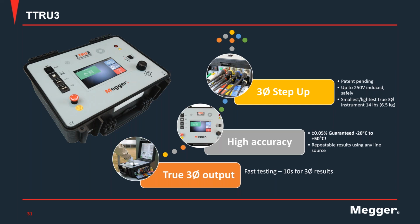And finally, the third major feature is three-phase step-up. It's a patent-pending algorithm that will actually perform a step-up test, assuring that the instrument will never have to deal with voltages more than 250 volts. So the unit will check the ratio of the transformer and then adjust the output. So again, you never will deal with more than 250 volts.